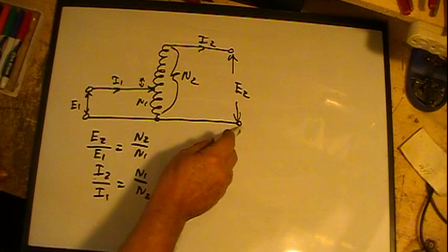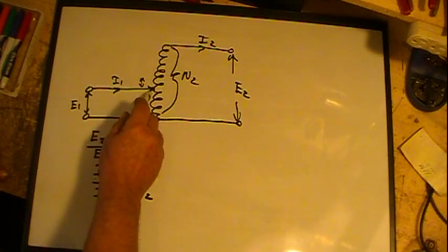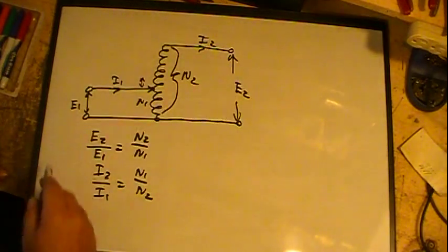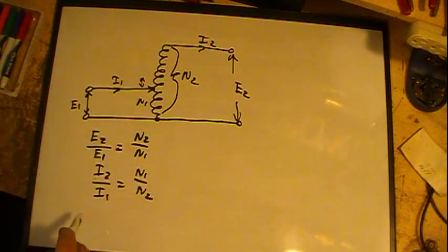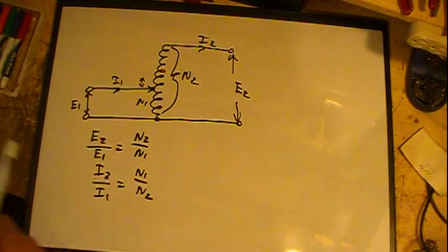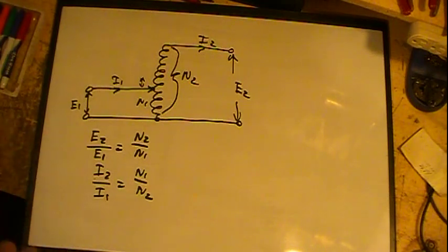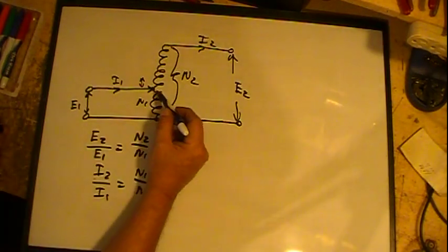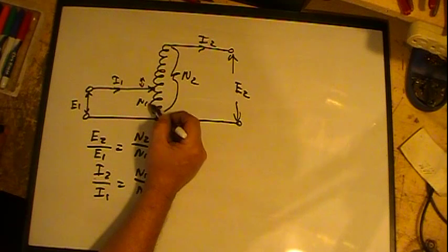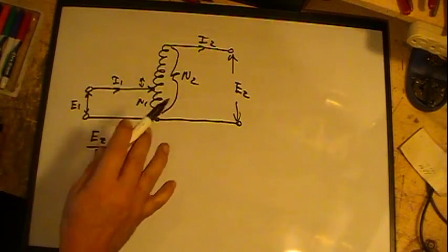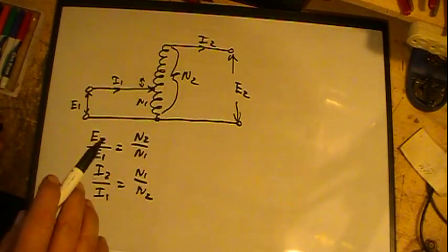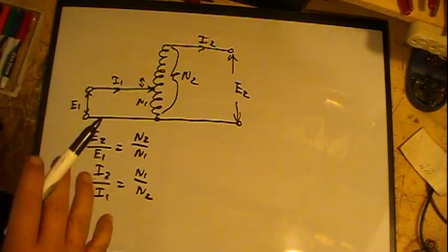This lead goes straight through, this lead is hooked in here and going through around. So there's no isolation. Your variac, just a plain Jane variac, is not an isolation transformer. Other than that, they work the same. Basically all it's doing is building a magnetic field in this winding, and we'll go deeper into how transformers truly work. Right now we're just doing an introduction.